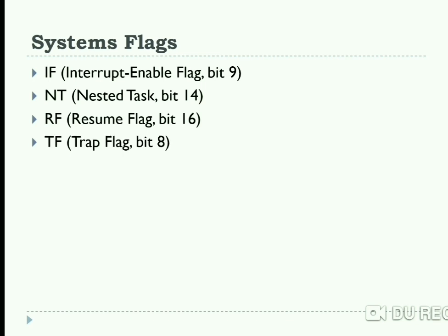Next is the trap flag. When we set the trap flag, the processor goes into single step mode, that is a debugging mode. In this mode, the CPU automatically generates an exception after each instruction, allowing a program to be inspected as it executes each instruction.